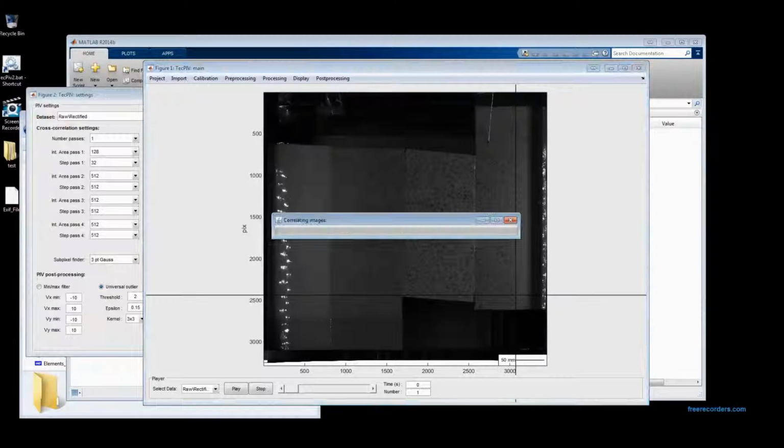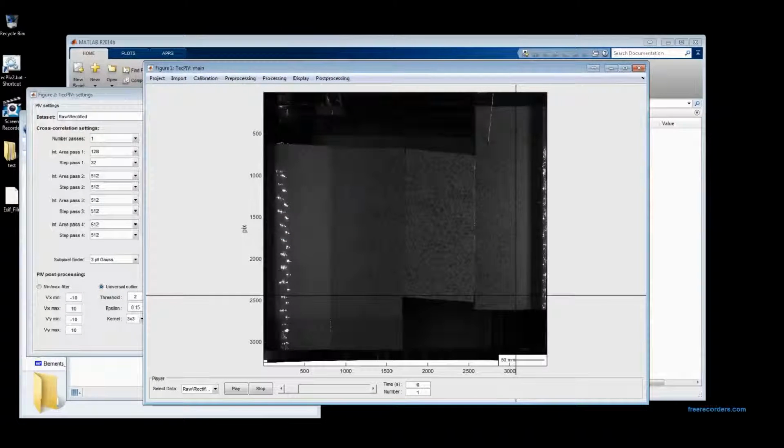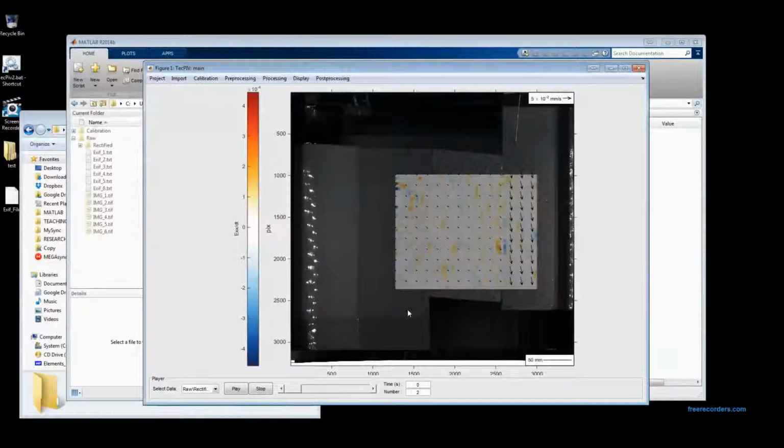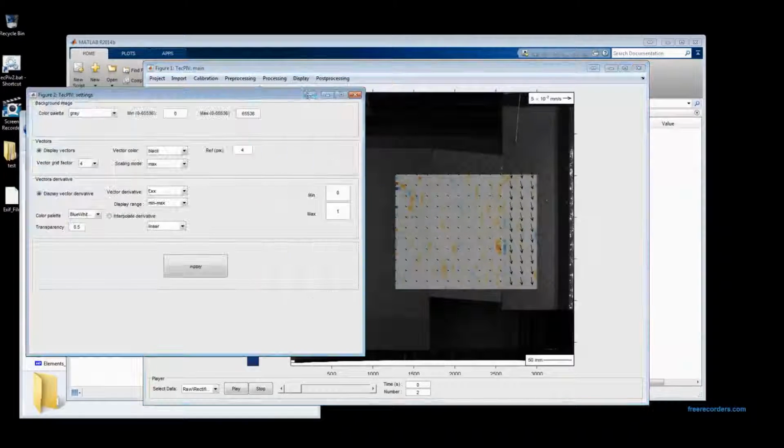We can show the derivative here, yx, and we can interpolate the derivative. That's showing us where the shearing occurs along this edge of the model. Nearly nothing is happening on the other side. Now we can change the color scale. We have almost nothing positive, nothing negative, so we can change to a color scale between white and blue, for example. Apply. Alright, so here it shows, but we still have our 0.